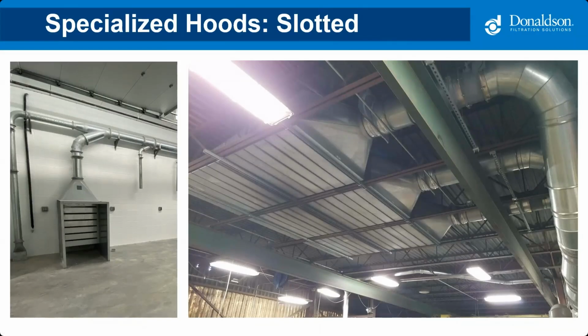You also may see something similar to the one on the right that's really common, is where you put a big hood over the top of, say, a robot welder, or sometimes you see them over the top of a small plasma cutting table or weld area. If it was a large hood like you would see in the picture on the right, you would have a big rectangular opening with what's called an impact plate, which is just a flat plate on the inside of the hood with about a 2-inch open perimeter around the edge.